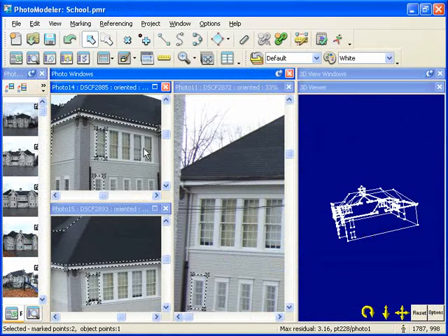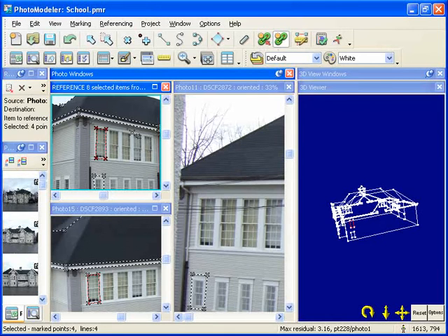All of our photos are oriented, and these points around the photos are referenced between these two photos. If we select them all and go into referencing mode, this will demonstrate Auto Drive. When a point's 3D location is solved and you're adding additional references for it on an already oriented photo, Photo Modeler knows the approximate location this point will be. When you are over the photo, it drives the mouse to this location. Move over photo 1, and our mouse automatically drives to the matching location for the yellow highlighted reference point.